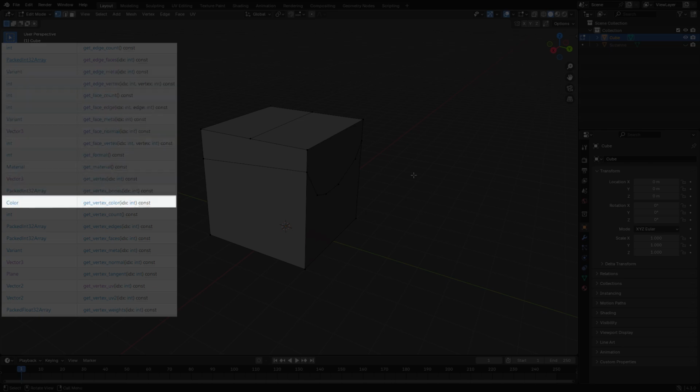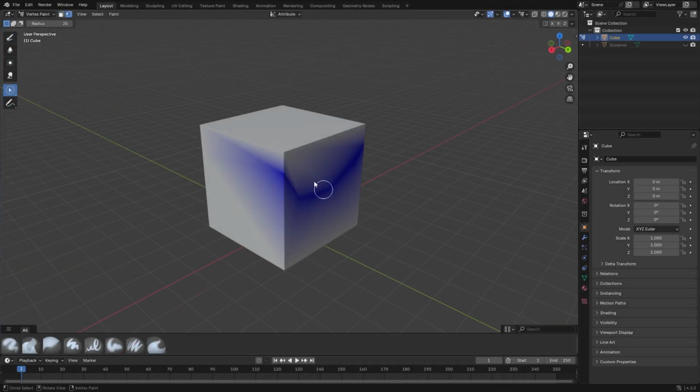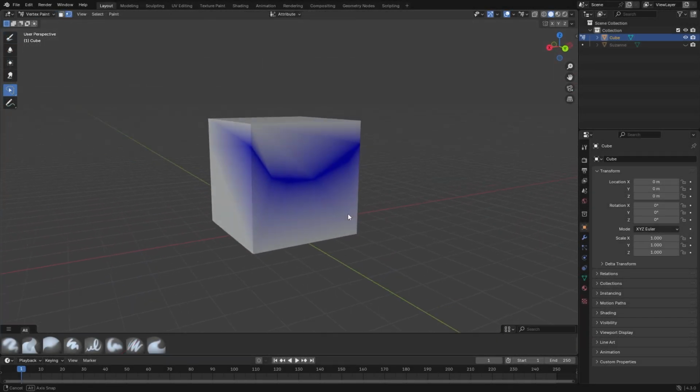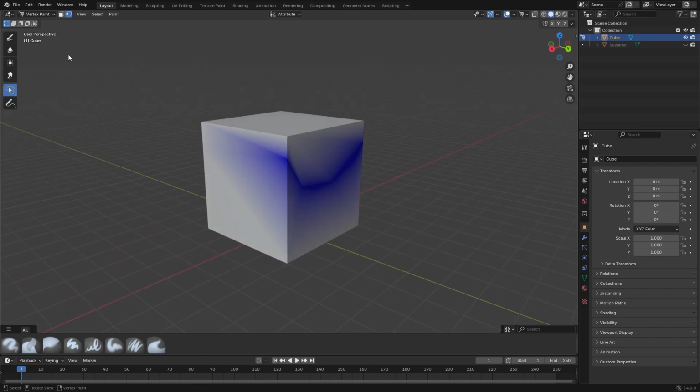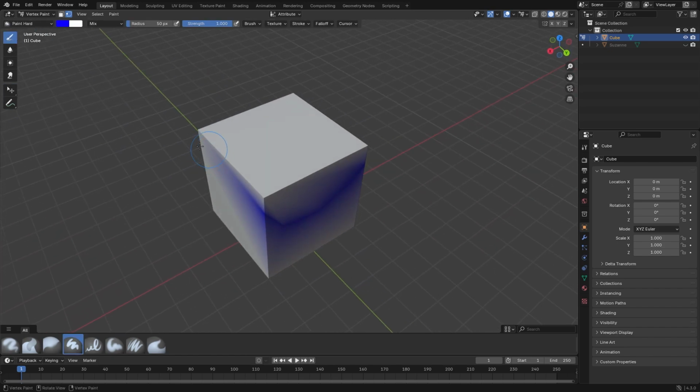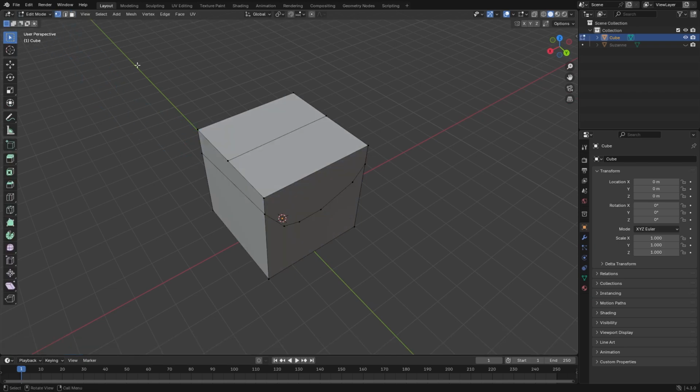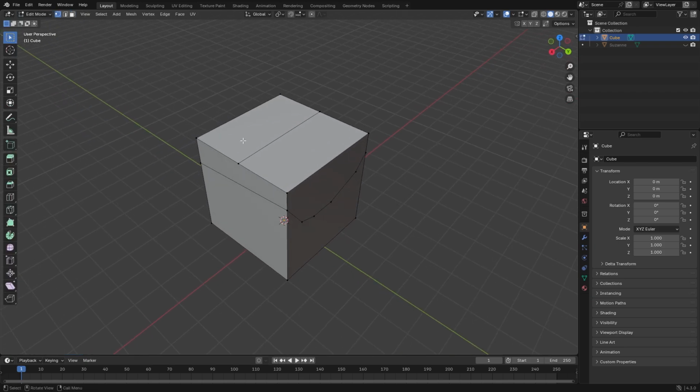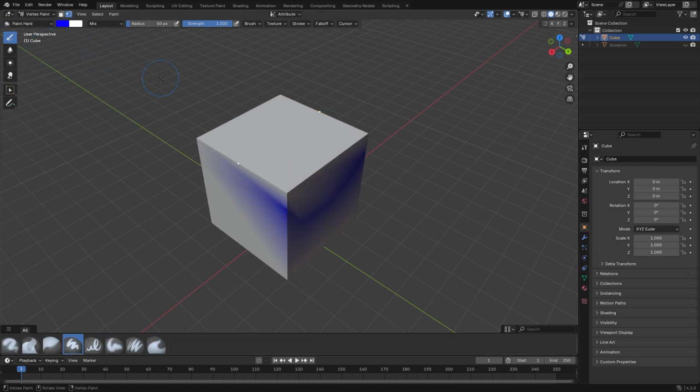The second option is vertex color, but first, I kinda hate Blender's approach to it because it makes your wall mesh into this gradient mix. It really promotes the artistic, non-discrete way of setting things up with brushes, etc. But we want to pass some discrete data, so what you will end up doing is you will select some vertices in edit mode, then change mode to vertex paint, then select vertex selection mode inside vertex paint, and then manually set the color of these vertices.